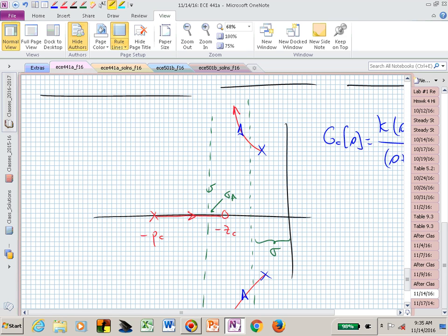Now, what we have seen maybe in the first part of the last lecture is that the more zeros we have, the more they really kind of mess with our percent overshoot. They make it worse. So we really don't want to just load up on zeros and make those close to the imaginary axis. Those will deteriorate our pure two-pole system behavior that we've come to grow and love in figure 5.7. That gets kind of thrown out the window. And so now that's just a crude rule of thumb to worry about.